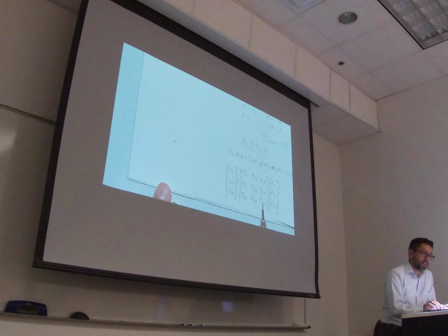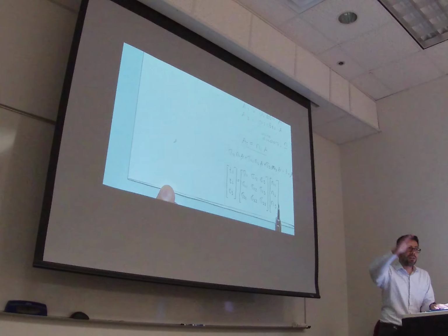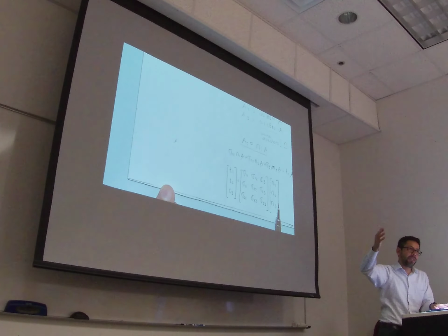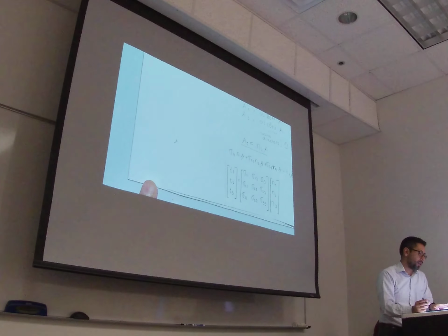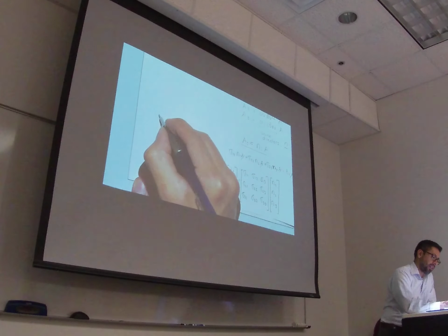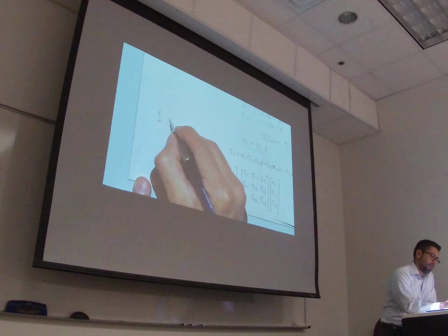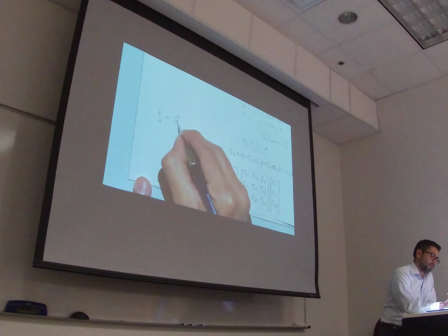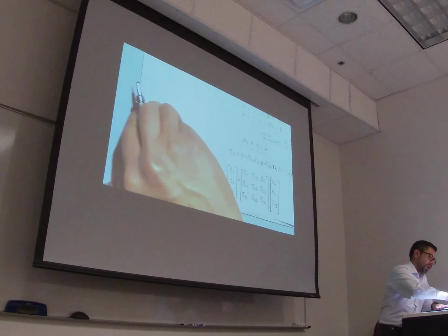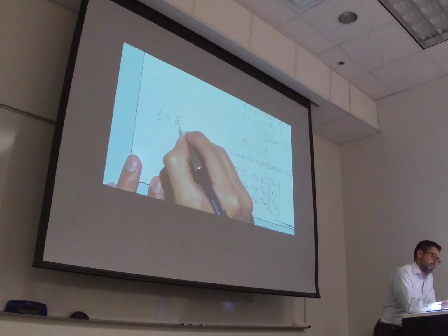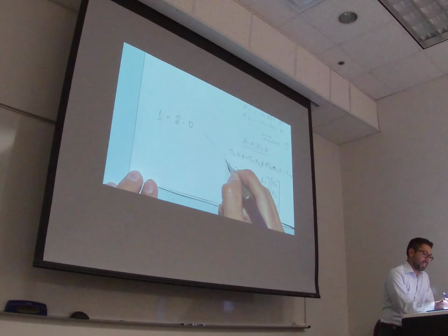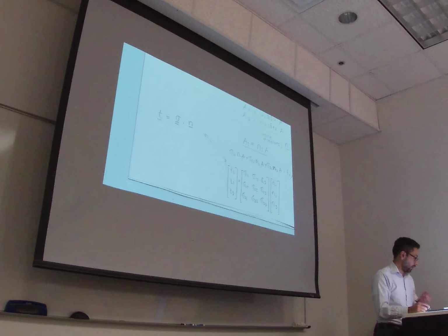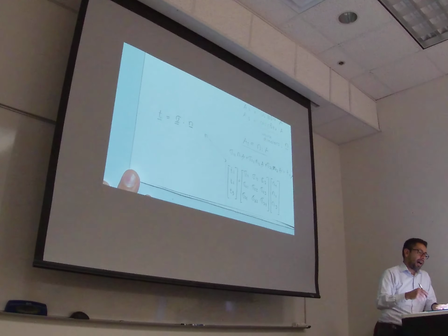We know what the state of stress is in a given location. We know what the vector n is, which depends on the orientation of a given plane in 3 dimensions, given by the direction cosines of a vector perpendicular to that plane. And this equation tells me that this vector T of the components of the stresses, T is a vector, just one line, is just equal to the stress tensor times the vector n, which is exactly the same thing I wrote here, but in a more compact notation. And this is the last step.